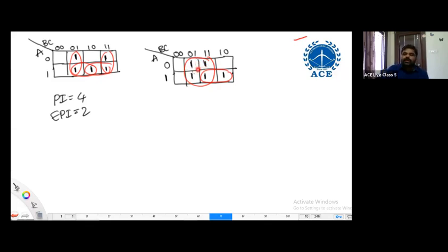In this we have 3. Yes, it can have more than one, not a problem. At least one cube is mentioned. Yes, in this we have only 1, but in this we have 3. But total groupings which are having special cubes is 2. So the essential prime implicants are also 2. Prime implicants 2. The essential prime implicants also 2. Then what is the minimal expression? This grouping is what? C plus AB. C plus AB. Correct? Because of the wrong K-map, whatever we are getting is wrong.